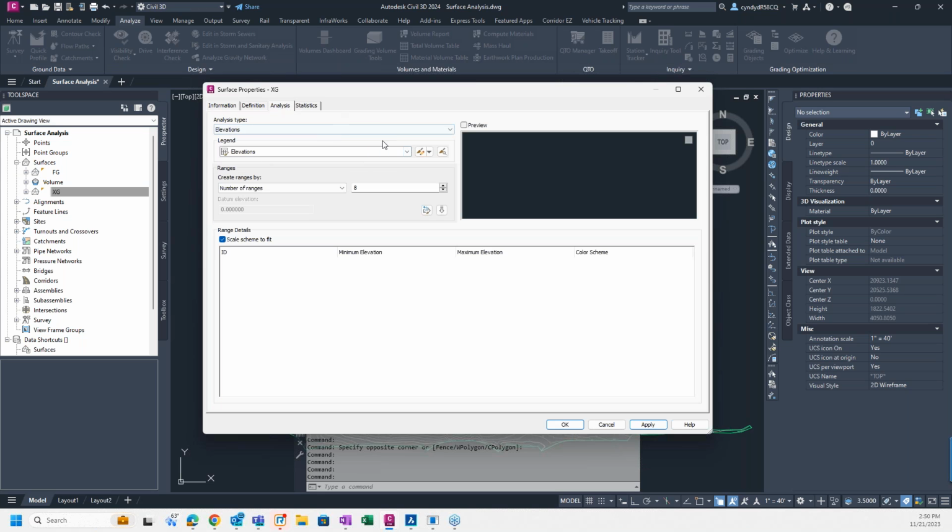A user contour analysis is what you run in order to highlight certain contours. You want certain contour elevations to be highlighted, maybe a thicker line, or maybe you want to make it in color. You can run a user-defined contour analysis like so. Okay, so what is that?